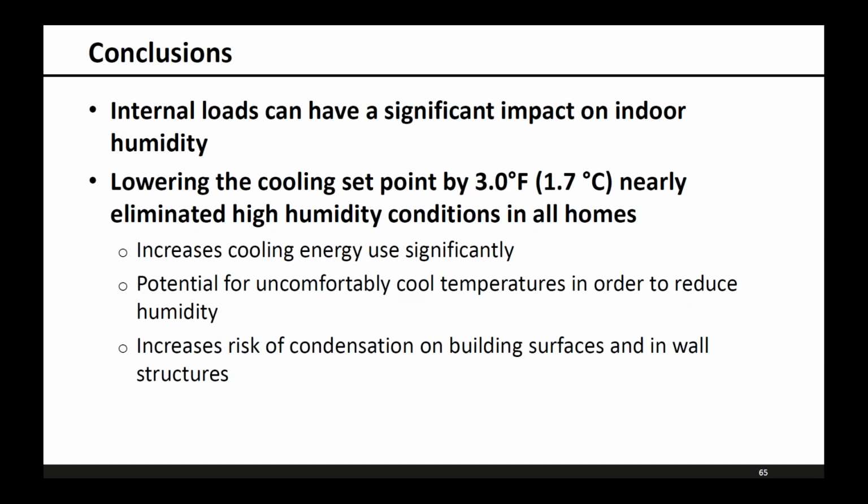There's also the potential to become uncomfortable due to how cold the indoor air has to be in order to control the humidity. And also running at lower indoor set points increases the risk of condensation and moisture durability issues in the building envelope due to condensation.